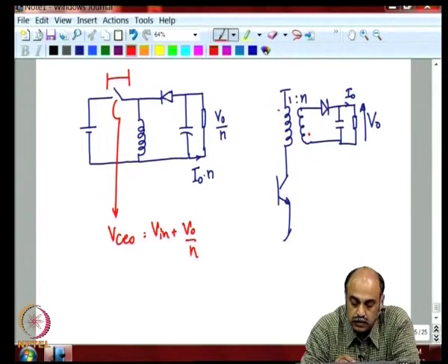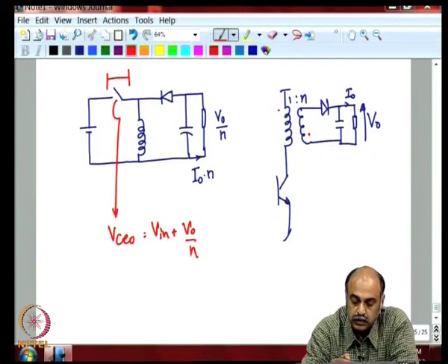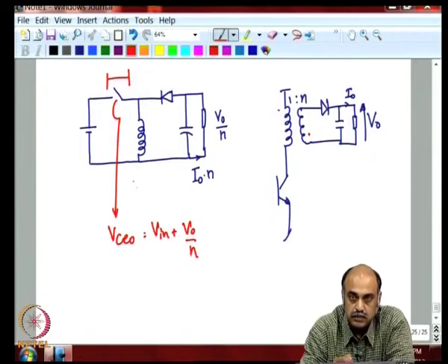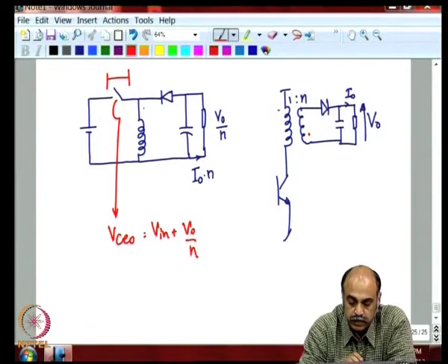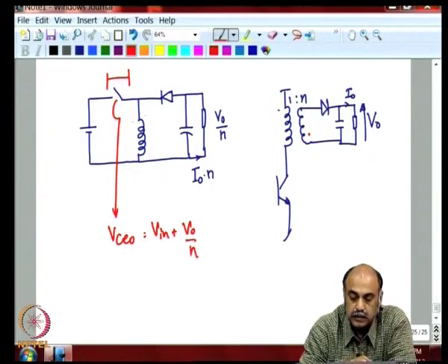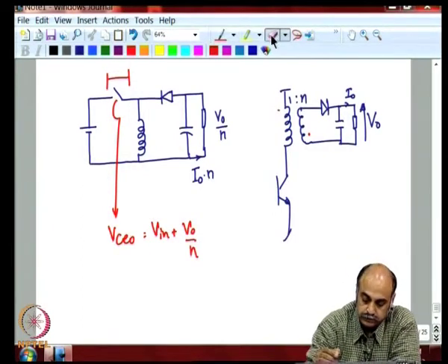And the inductor value can be calculated, and once the inductor value is calculated, find the energy to area product, follow it up with permeance, then the number of turns and the wire gauge. So, once you have decided that, there is a small modification you need to do at the inductor, and that is the K factor.